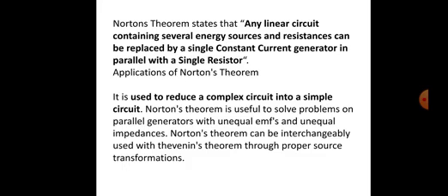The Norton equivalent circuit. Norton's theorem states that all linear circuits can be simplified to an equivalent circuit with a single current source in parallel with a single resistor connected to a load. Step 1: Remove the load resistor and replace it with a short circuit. Step 2: Calculate the Norton current, the current through the short circuit.